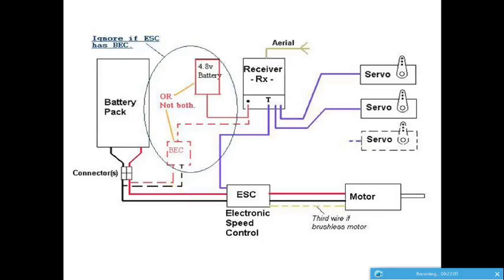Okay, so it's the same circuit diagram, but here they have explicitly mentioned some additional servo connections to the receiver. So the receiver will also have channels such as throttle, aileron, elevator, maybe landing gear, rudder, auxiliary 1, auxiliary 2, battery, etc., which is explicitly mentioned on the receiver pins.